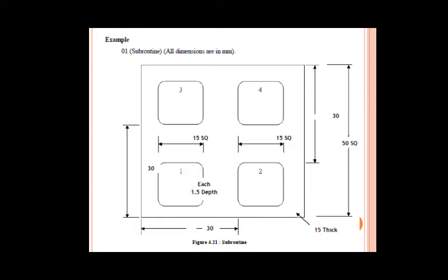Then you are supposed to move the tool over here, and again call the program at the third place. Whenever your tool moves over here, again you are supposed to call that program to make a pocket. Same for the fourth pocket also. Whenever your tool comes over here, you call that program to make the pocket in this plate.